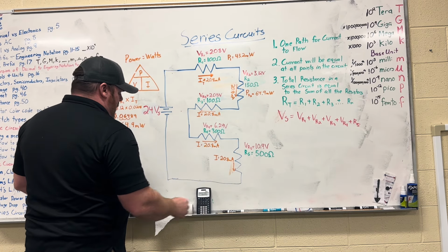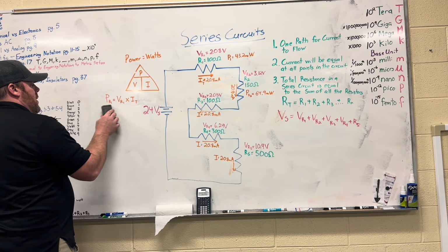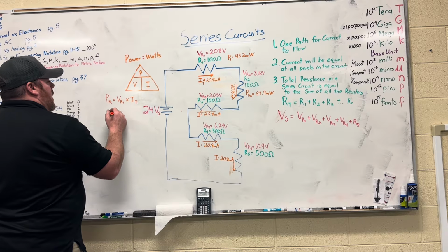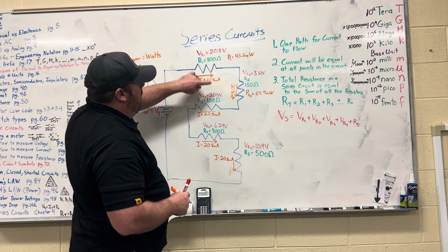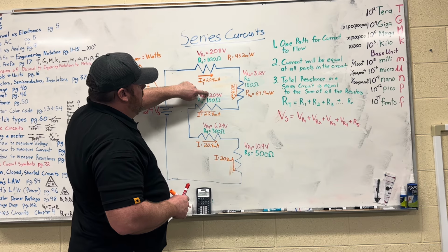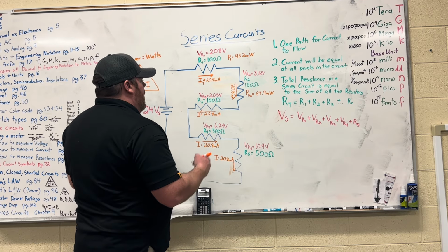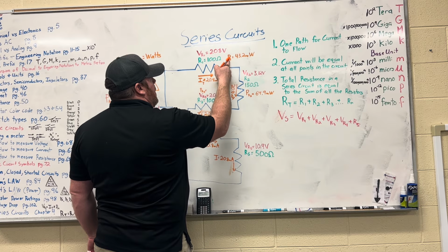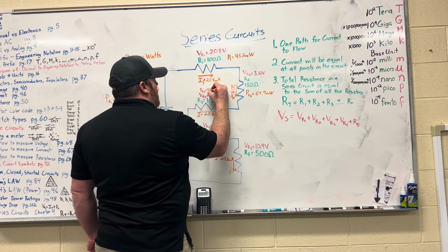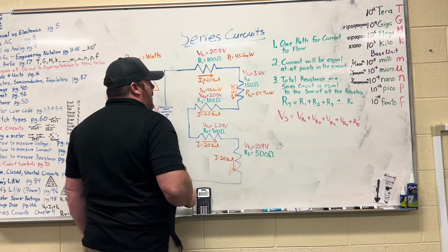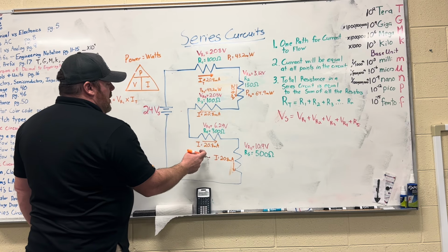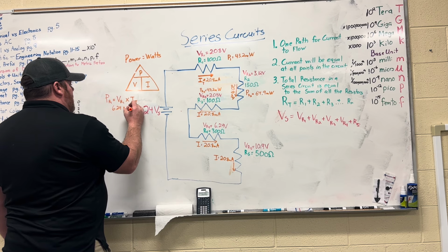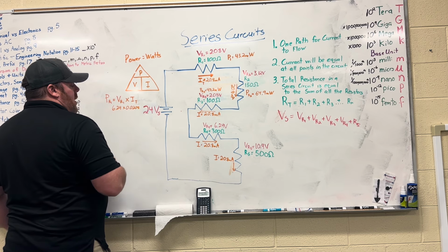We're going to repeat this for all 5 resistors. Same mathematical equation. We're just looking at the voltage drop times the total current. If we notice here, these two had the exact same resistance, the exact same voltage drop, and the exact same current. So we already know at this point that the power consumed by R3 is going to be equal to 43.2 milliwatts. So we're going to skip on down to this one. We have a voltage drop of 6.24 volts times the 0.0208 amps.